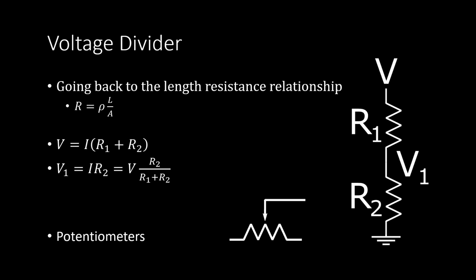If you're pulling current out at this point, less of the current is going to flow through resistor 2. So that can end up being problematic if that's a big percentage, or if that current is varying. A lot of times, if that current's constant, it's okay because you'll use these and manually set them. So if that's the case, it may not be that big a deal. But if that current that you're pulling out is fluctuating a lot, you may get large changes in voltage at V1.